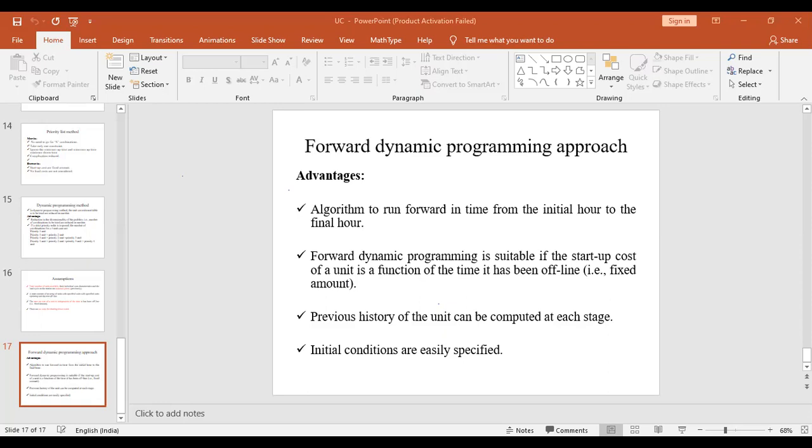This is a simple equation for a fuel cost function for the system connected with two units. Now we are going to calculate the amount of power generated by each unit. First of all, the total power generation between both units, PG1 plus PG2, is equal to 1000.